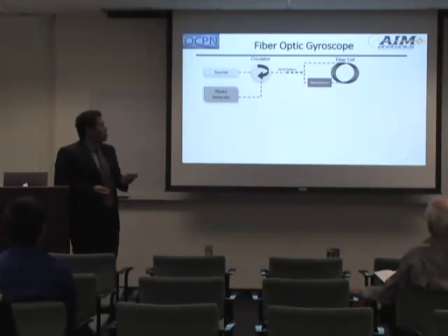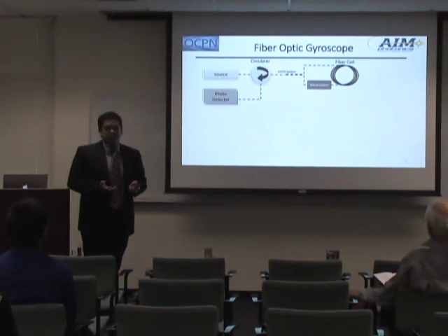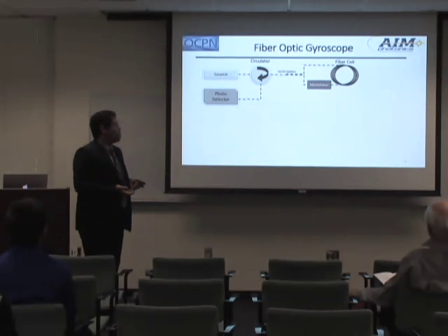And this phase modulator applies a phase bias to the light wave to bring our operating point to zero. So when it's at a standstill state, the photodetector will detect a voltage of 0. And so it makes it easier for us to detect changes in voltage levels when you rotate the apparatus.